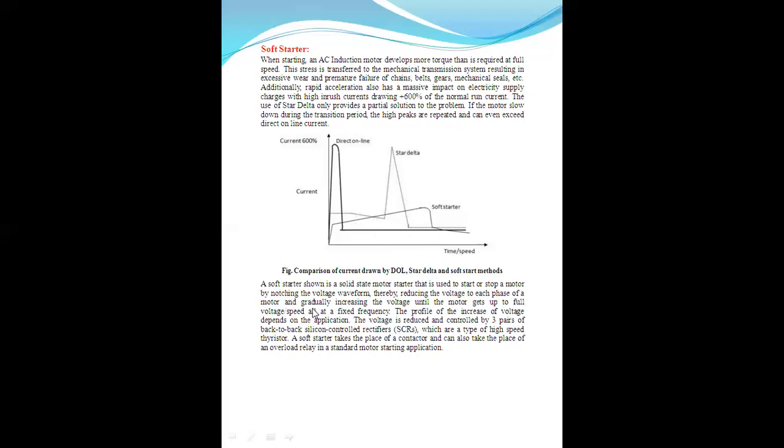A soft starter is a solid state motor starter that is used to start or stop a motor by notching the voltage waveform, thereby reducing the voltage to each phase of a motor and gradually increasing the voltage until the motor gets up to full voltage or speed, all at a fixed frequency. The profile of increase of voltage depends on the application.